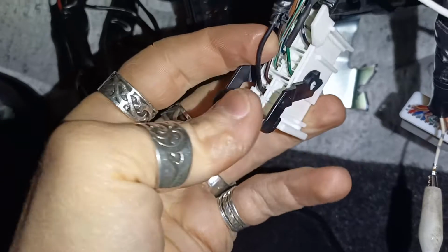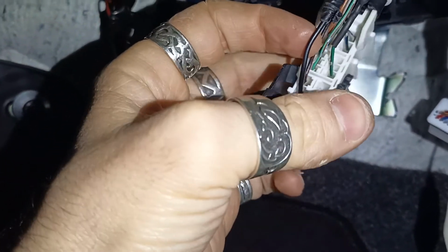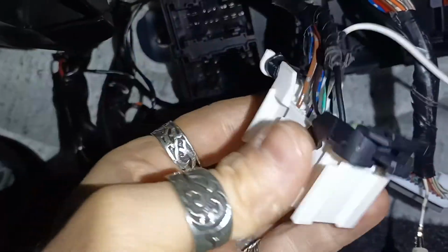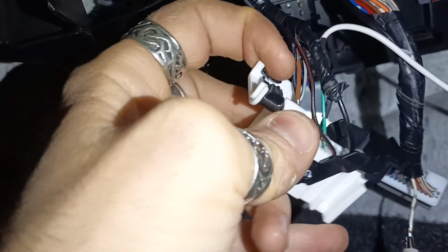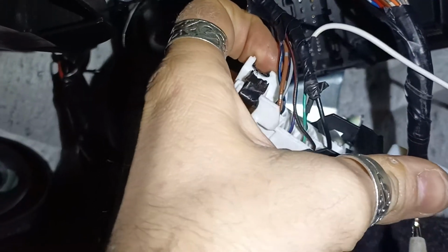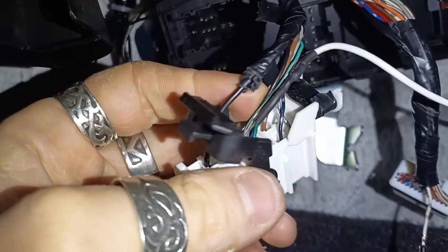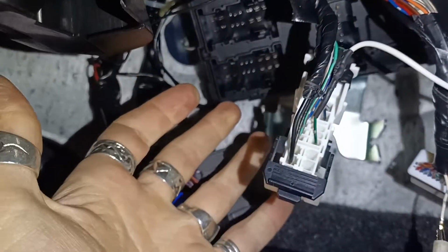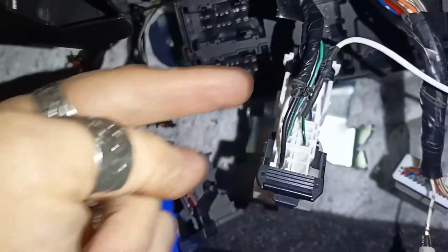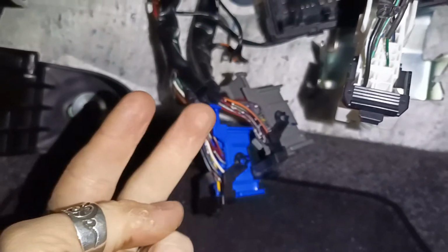Interestingly, this wire doesn't exist in the documentation, but there is, see that bluish wire here, blue with black, that wire here, blue with black. That wire from this side looks almost pure blue, pure black. That wire right here, according to the documentation, is pure ground. Now I have tested, they are both pure ground. I'm going to use this one since it's already spliced. So this covers the first 2 things, getting the ground and power.